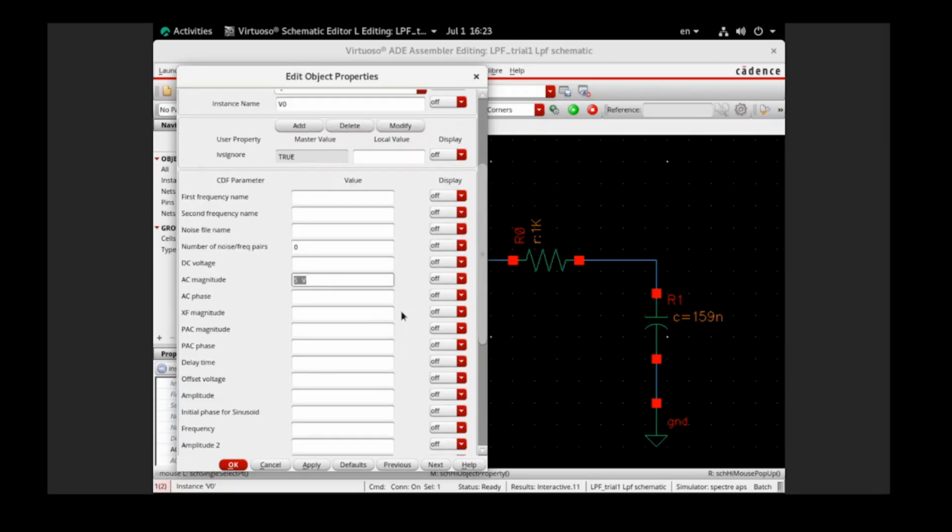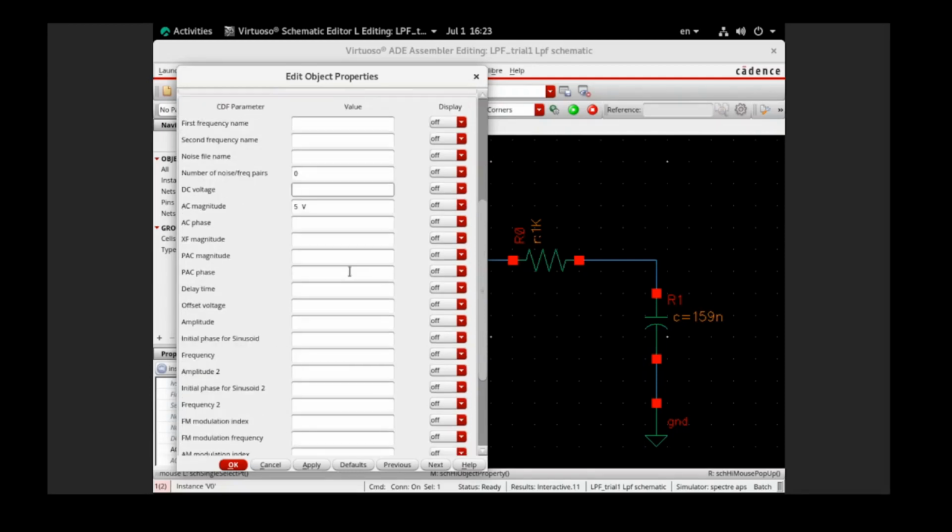And in order to do so, you can see that there's an amplitude, which is the amplitude of our input sinusoidal, and the frequency. We need the frequency. So this is the frequency. To make it easy to observe, of course, let's put it at 1 volt. And for the frequency, we first test with a frequency lower than the bandwidth frequency.